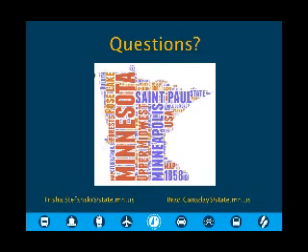Okay. I think you answered this next question already, but we'll throw it out there. Does the GIS shapes have Z coordinates, and if so, do you use them in 3D GIS viewers? Well, the guardrail would have a Z coordinate, but we're really not utilizing that coordinate information. We're utilizing it for our drainage structures, which have a Z coordinate on the pipe within the structure. For design purposes, that's very important. But for guardrail, no. Right now we're focusing on a two-dimensional asset management approach.